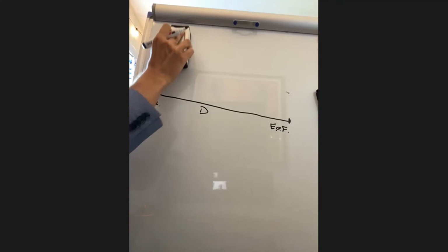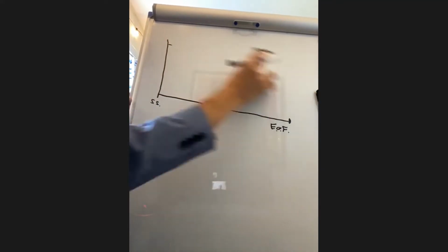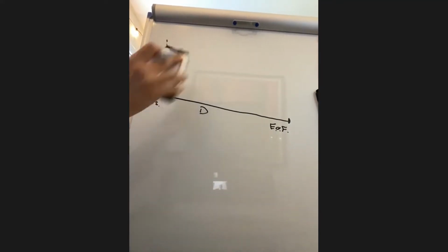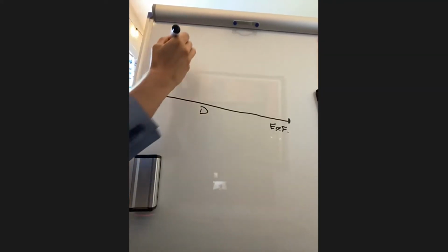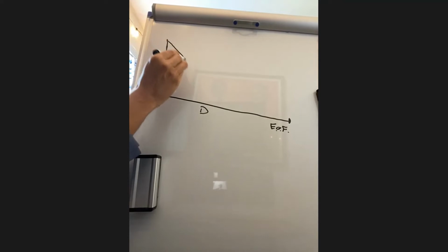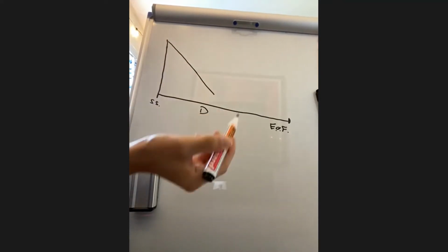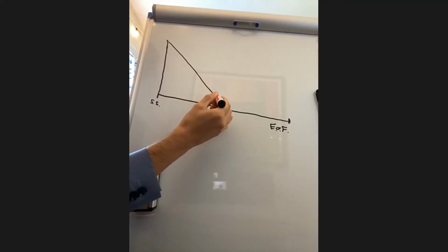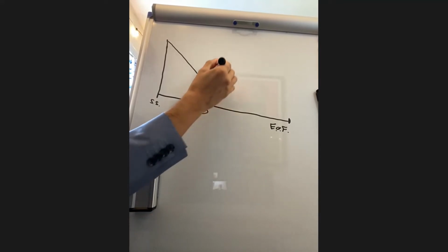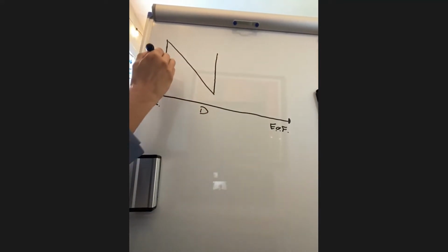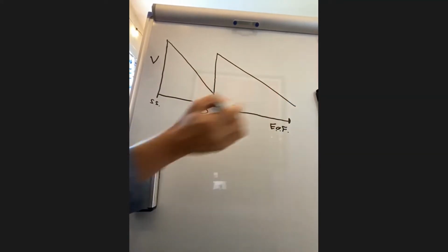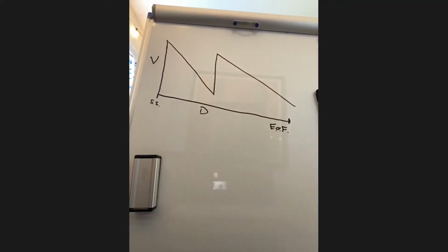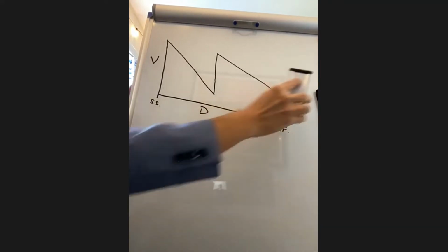So during the winter and during the summer, power usage is extremely high. So voltage drops very quickly. And so essentially what you'll do is coming out of the substation, voltage will drop pretty quickly. The distribution utility will install a capacitor bank or a voltage regulator or something like that to raise the voltage back up, and then it can continue on down the feeder. So that's what the voltage profile of a distribution circuit would look like during winter peak or summer peak.